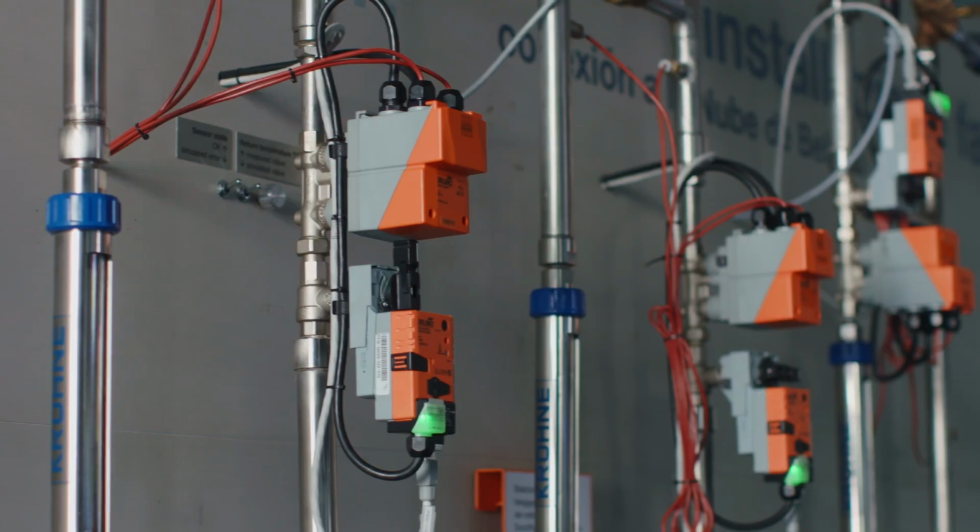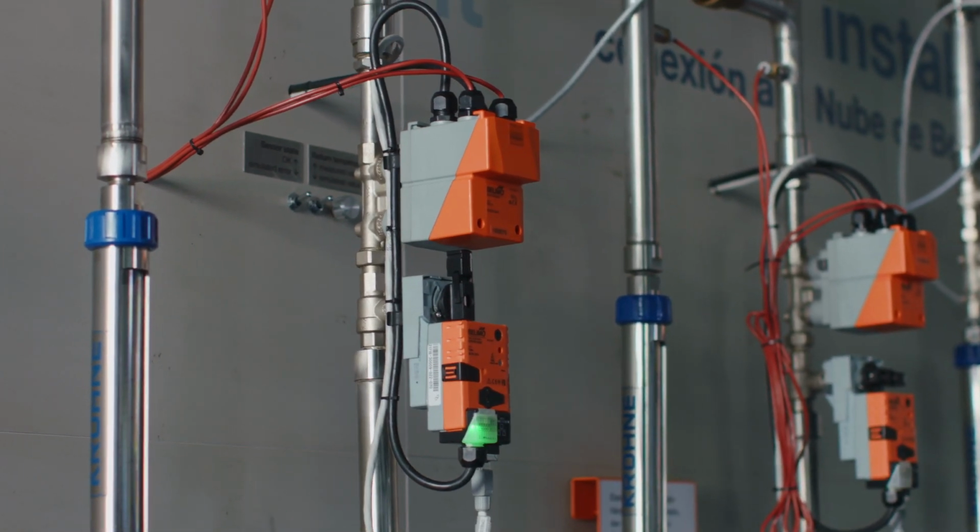Belimo, like most reputable manufacturers, design their valves for a very long life expectancy. However, there are very few ways of actually detecting when that unseen pressure regulator has failed. Okay, let's talk about electronic pressure-independent valves. Introduced around 10 years ago, they all consist of a control valve and a method of measuring flow.